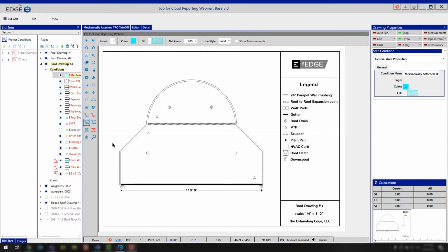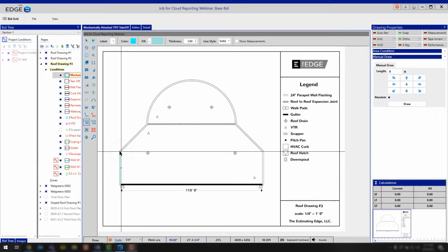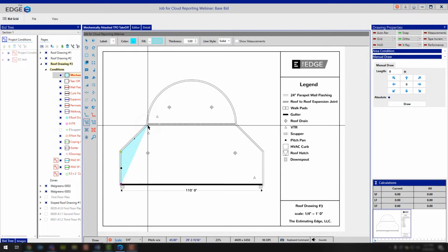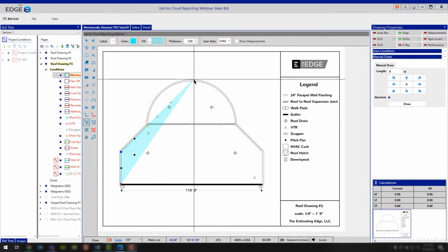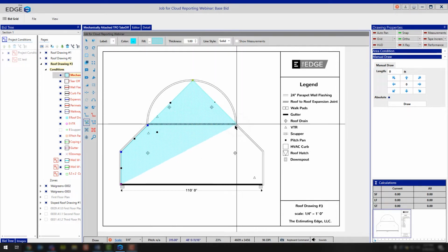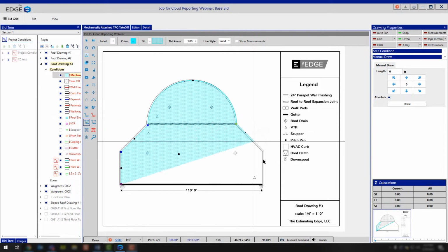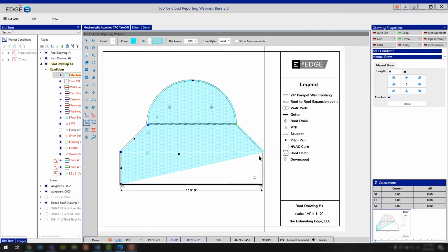Left click on your area tool to activate it, and then ultimately click your left point, your first point, with a left click, and then just keep left clicking to draw the additional points. Now in this case, we're going to cover that Convert to Arc tool. It is based off of the last 3 points that you click. So in this case, this is point number 1, here's point number 2, and here's point number 3. Move over and click the Convert to Arc tool, and move your mouse back over and you'll see that it's converted the arc for you.